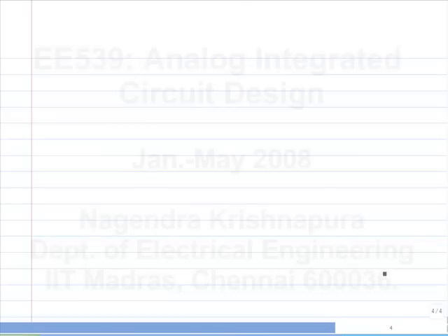Now, a frequently used term, we didn't even talk about things like phase margin, but it's a related quantity. So we did the complete analysis in the frequency domain and some in the time domain to figure out what's happening to the feedback system. And from that came the criterion that to get a critically damped response, the second pole has to be 4 times larger than the unity gain frequency of the loop, and so on.